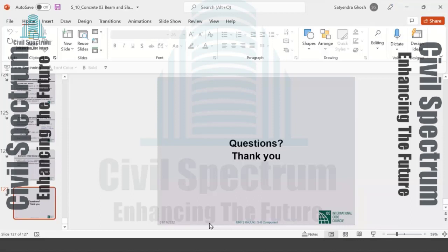How should we consider shear rebar in an arch beam? Arch beam, you don't need shear rebar, do you? An arch is compression. The whole idea is that you are carrying loads in compression.